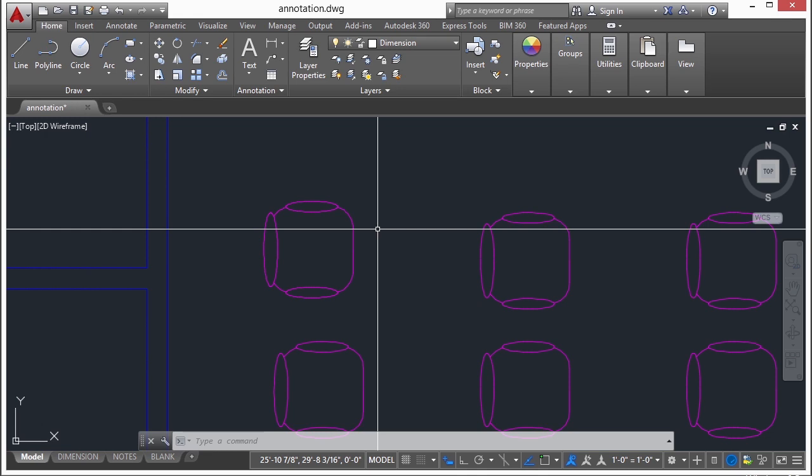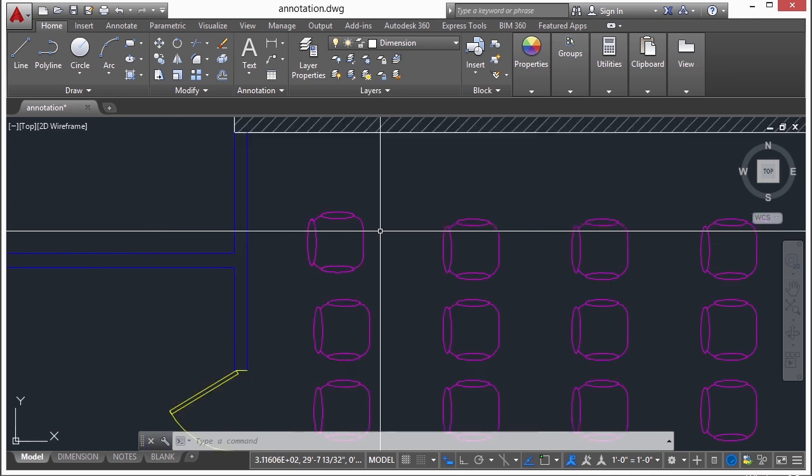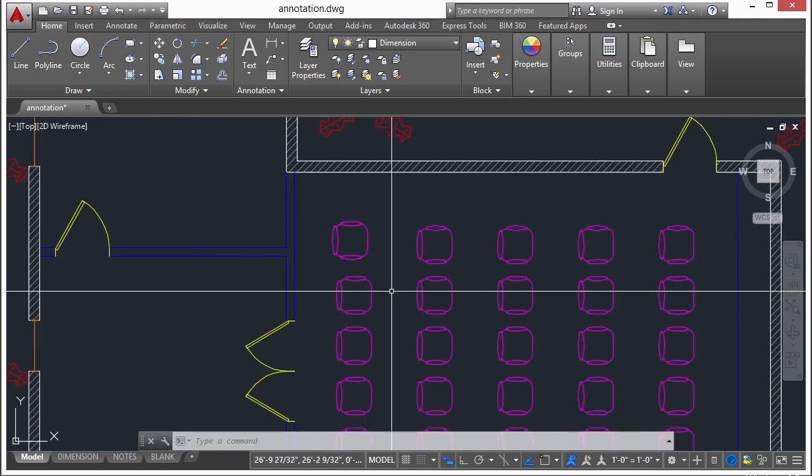Blocks are meant to recreate objects quickly, like the chairs and the doors that you see here. They can be copied, rotated, scaled, moved, erased, and more. They can be saved, inserted, and used again. You can export them as their own file so that you could use them somewhere else with a W block command. And it's also a good practice to create a block library somewhere.